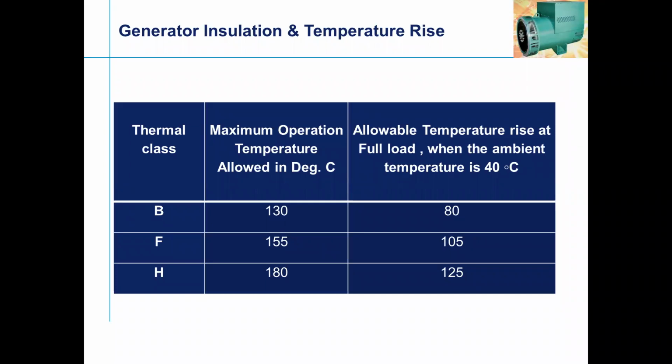Of course, in India, as I said, there is 48 degrees in Rajasthan, and at some points in Andhra, Vijayawada, as well as Nagpur, the temperature can even touch about 49 or 50. So in those areas where the summers are hot, class H insulation becomes predominant, where the generator canopy and other things can see temperatures up to even 45 or 50 degrees. So generally the customer requirement has moved across from the very late 80s.